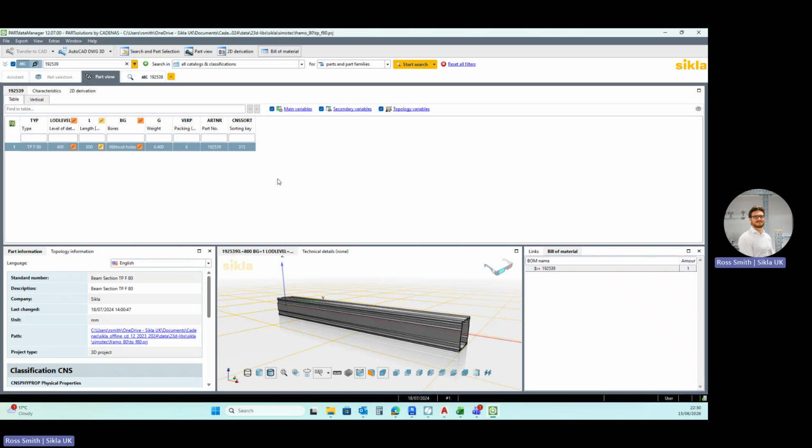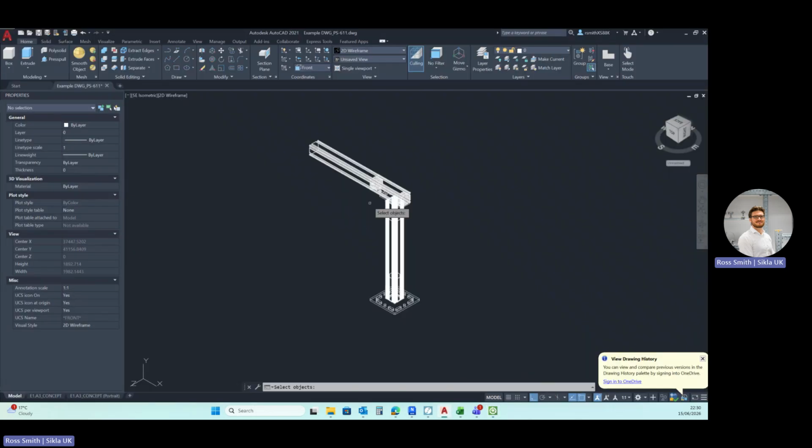There's not too much feedback at this point, but know that when you re-enter AutoCAD, select objects has become available. So I'm going to left click, right click to create a crossing box to select everything, and right click to accept. Okay.